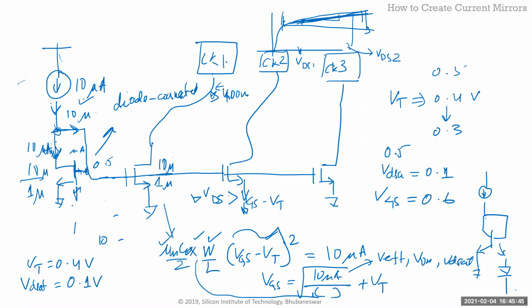So that's why it's called a diode. So it's actually not a diode in MOS, but it comes from the BJT world because that's how mirrors were done in the BJT world, right? Same principle. It's just that in the BJT world, you have more error because you have base current. So you're stealing some base current away. If your beta is low, you get more base current, but that's where the diode connected comes into the picture.